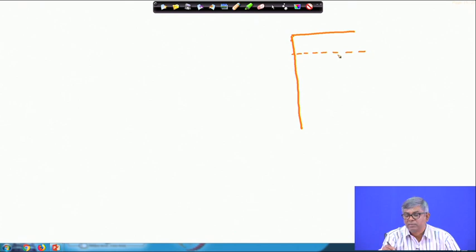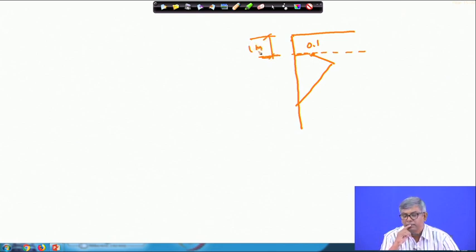So, that means your diagram will start from here and since it is a square footing, the value here actually 0.1, and since it is a square footing, maximum will be at B by 2, so that will be somewhere here, and the maximum will be at 2 B depth. So, diagram will be something like this and this is 1 meter, first layer is 1 meter and second layer will be,